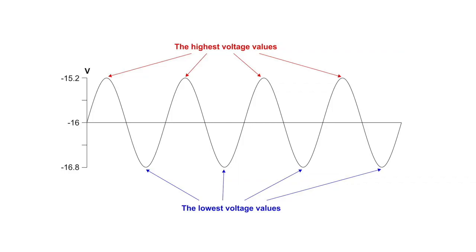Now we switch the view to the gap values. But it's confusing. Usual understanding for measurement of anything is that the higher output voltage from the sensor means higher physical value. For example, higher voltage means higher temperature, higher pressure, and so on. But we can simply fix it on our analyzers. We only need to set correct values of sensitivity and offset. We need to set negative values for them.